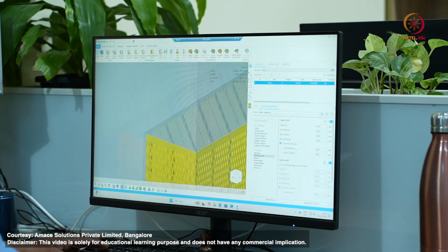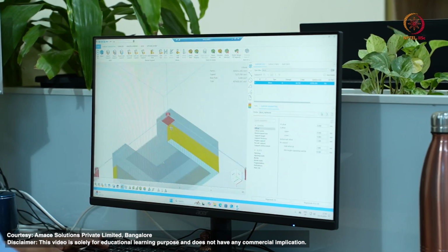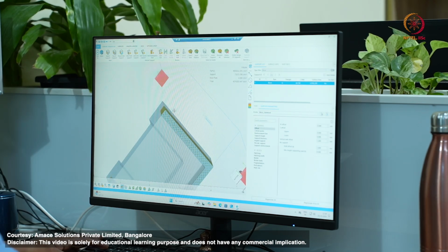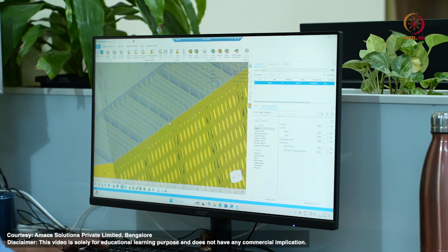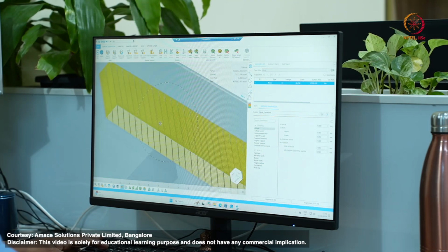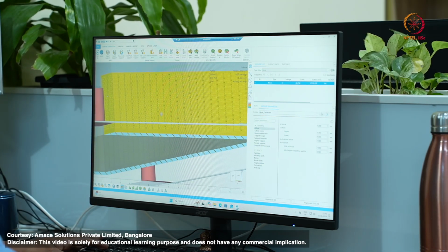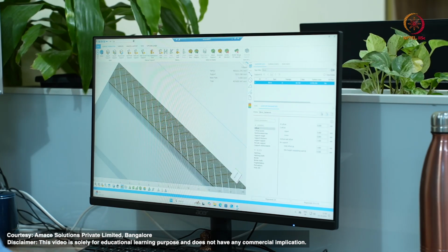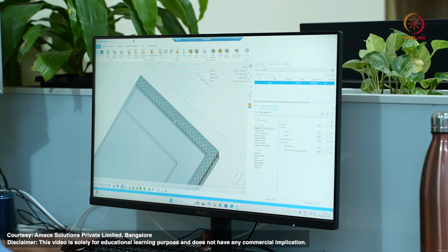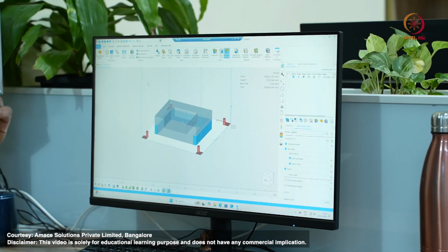So if you see here, you will be able to see. These parameters you can change according to your machine as well as the printing parameters. So in block support, the main factors we need to consider are the perforation which is required for powder removal from the supports, then fragmentation for ease of support removal. So once we have done this support generation, we can slice the file.